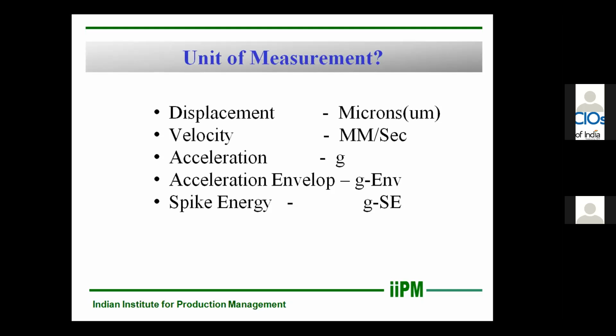Spike energy we use in most cases to identify defects in the bearing, because whenever a bearing has a defect, it will generate a peak in the ultrasonic zone.